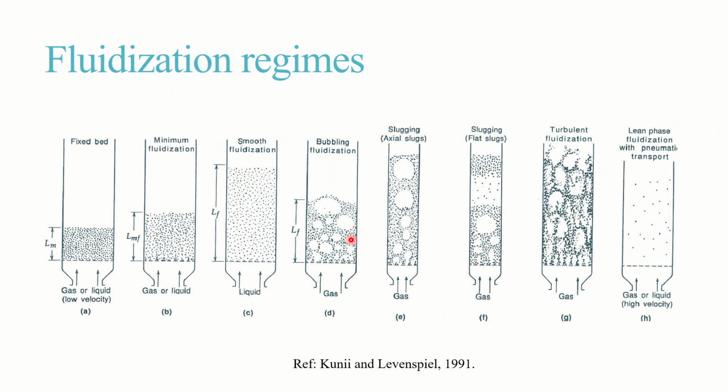So, depending on the application, the bubbles in turn slightly affect the mass transfer happening between the particles and the fluid. Bubbling fluidization is understood. But in the liquid case, however, bubbling is not observed in most cases. This is known as smooth fluidization when we are dealing with liquid, and when we are dealing with gas, it is bubbling fluidization.